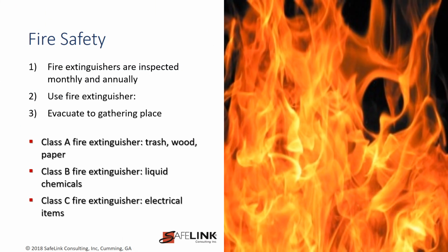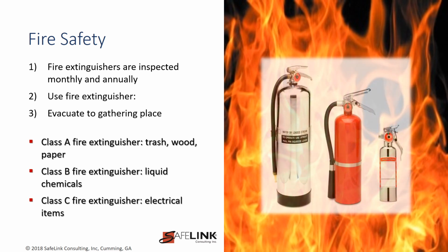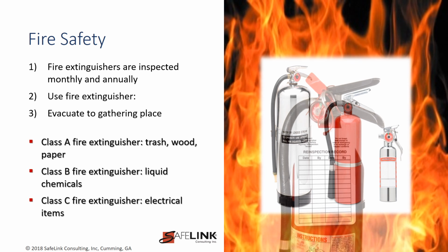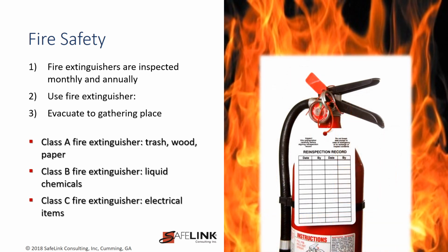Fire safety is important in your facility. Fire extinguishers should be available in the event of a fire. Fire extinguishers should be inspected by a designated individual monthly and by an outside company annually to ensure they are in good working order. Individuals who may be expected to use an extinguisher in the facility must be trained on its proper use.